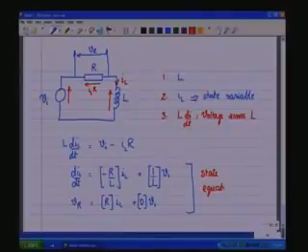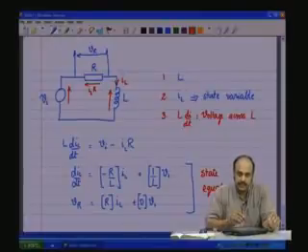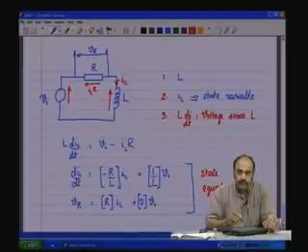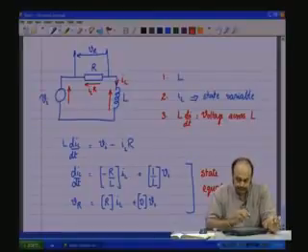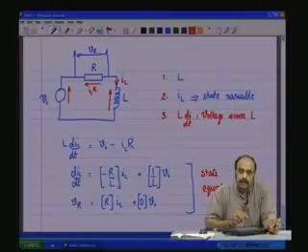You see, it is so simple. Actually, whatever be the complexity of the circuit, you just have to follow these three steps. Step 1, identify the energy storing elements. Step 2, identify the state variables associated with these energy storing elements. Step 3, with no particular order, starting at any particular energy storing element, the equation describing its dynamic behavior can be put down, and then followed by the equation describing the dynamic behavior of all other energy storing elements in the circuit. So, that is the method that we will be following.